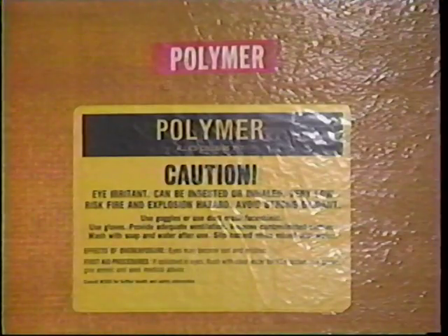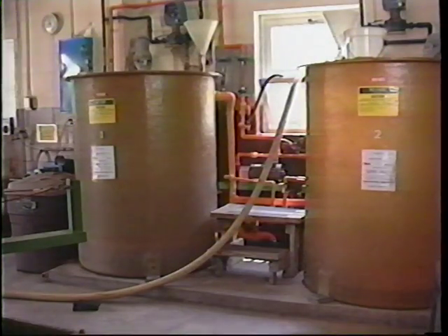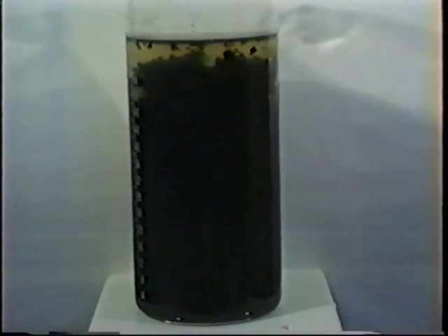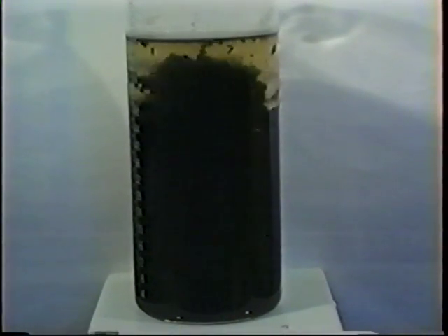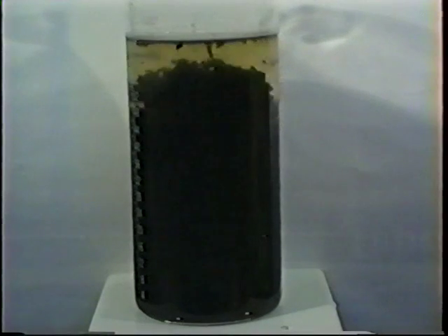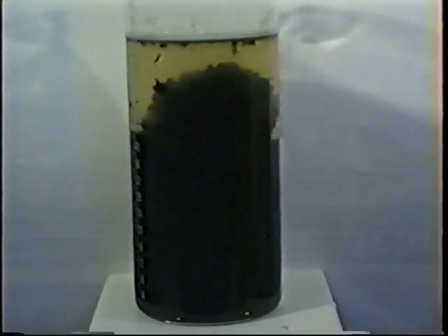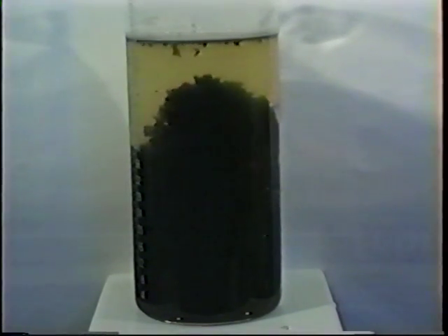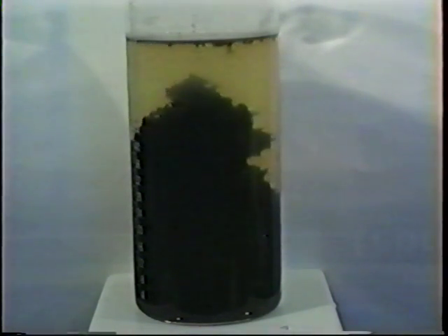You may find chemicals being added to the influent of some clarifiers in order to enhance performance. With clarifiers that have sporadic heavy hydraulic loadings, the use of polymers may be necessary to enhance the settling characteristics of the solids in the wastewater. The polymer causes the particles in the wastewater to coagulate, thus forming bigger and heavier particles which will more readily settle. The use of polymers can get quite expensive, and it is usually not considered part of normal clarifier operation.